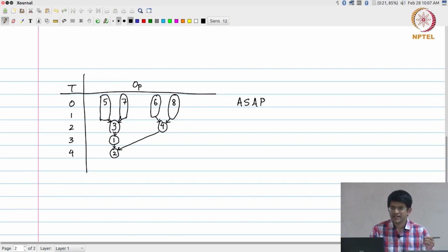If I now try and identify, if I wanted to directly implement this, what are the results that I end up with? This would basically imply, first of all, n is equal to 5, right. I need a 5-phase clock in order to implement all of this because it takes 5 time steps to complete one iteration. Number of multipliers is determined by how many multiplication operations are initiated at any given point in time, the maximum among those, right.